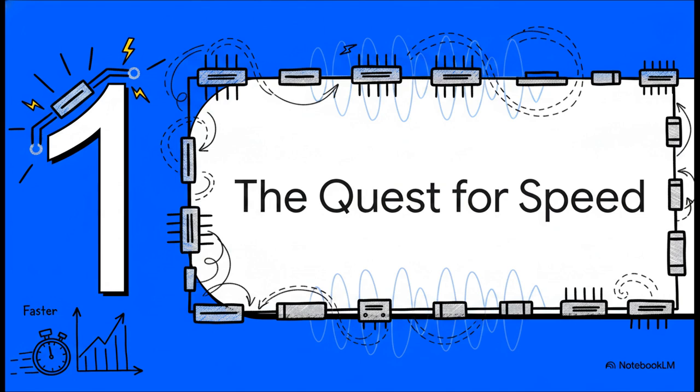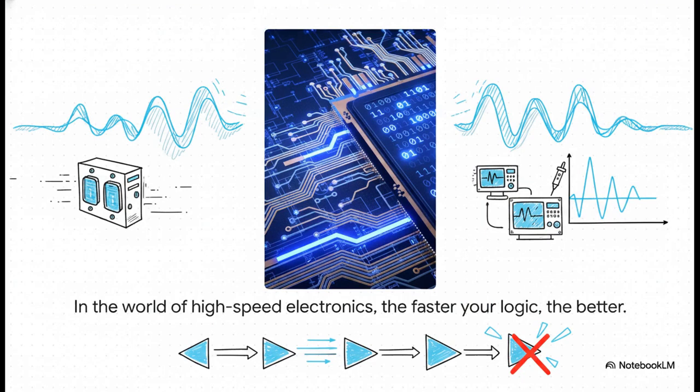Okay, let's start at the very beginning. Why was ECL even invented? Well, the answer's pretty simple: the relentless, never-ending quest for more speed. Look, in things like high-frequency communications, supercomputers, you name it, the speed of your logic gates becomes the ultimate bottleneck. Your standard logic families, they just can't keep up. And this performance gap is the exact problem that emitter-coupled logic was designed to solve.